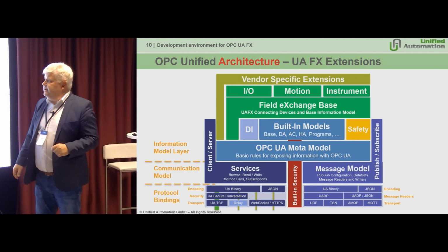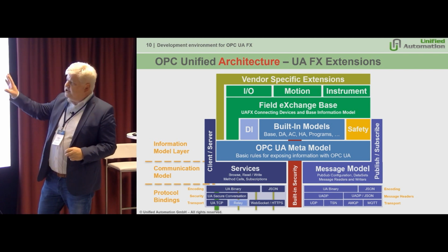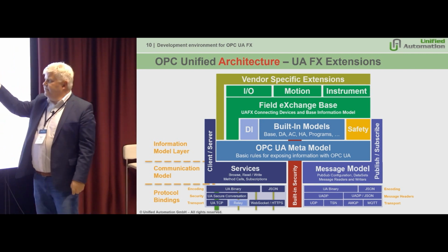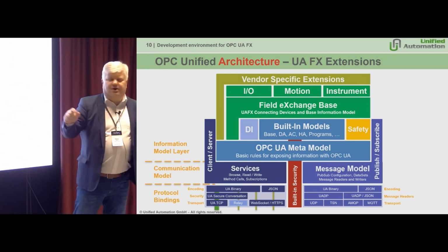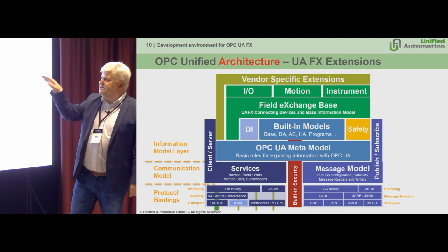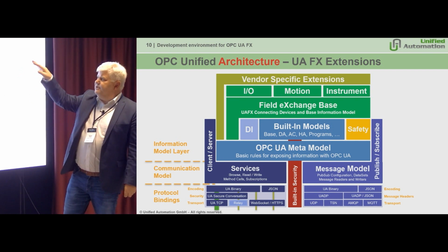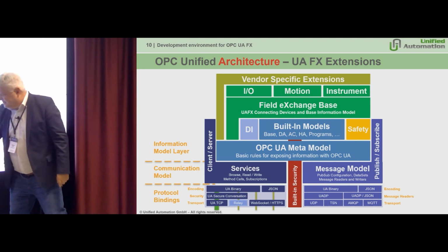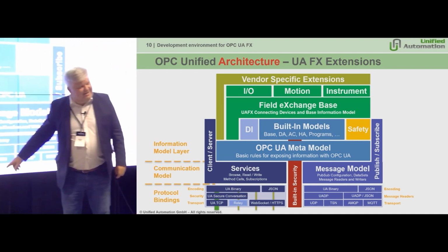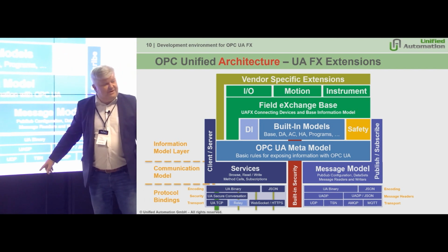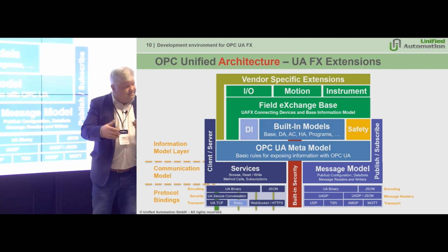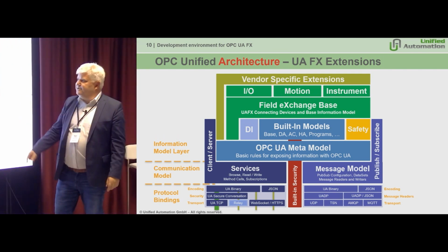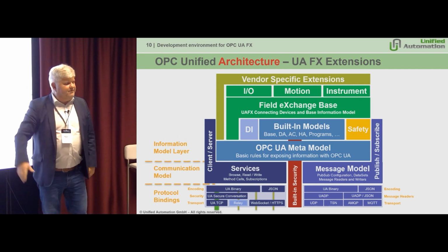Okay, so in the big picture, in the architecture picture, most of the FX stuff is on the information model level. So all the connecting devices, base information model, also I/O, motion, instruments. And if we talk about this layer, there are some definitions also in FX or referencing standards, but in the architecture picture of OPC UA, I would say most of the functionality is up in the information model.